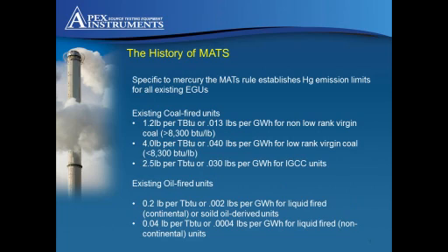So turning our attention to mercury specifically under the MATS rule, the limits are determined by a couple of things. One is the fuel source that you are burning, whether it be coal or oil, and secondly, the allowed mercury limits under each fuel source are determined by the subcategory of fuel you are burning.